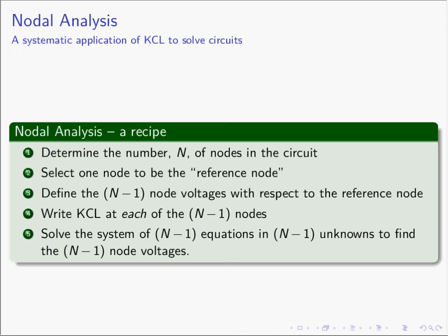As a review, nodal analysis. Remember, nodal analysis is a systematic application of KCL to solve circuits. We have a recipe, 5 steps. If we have n nodes in our circuit, then we are going to expect n-1 equations, KCL equations, in terms of n-1 unknowns, which are the n-1 node voltages.